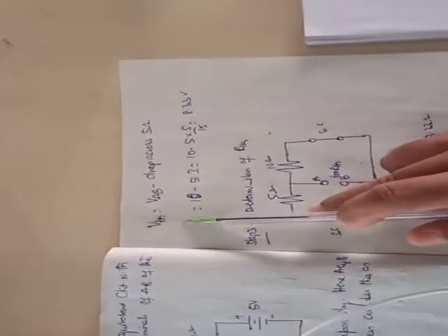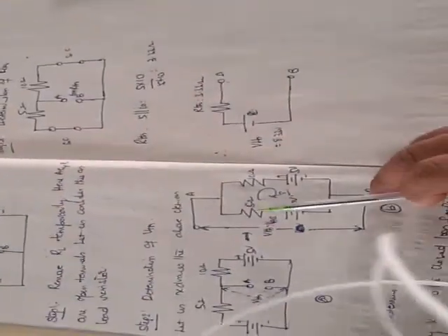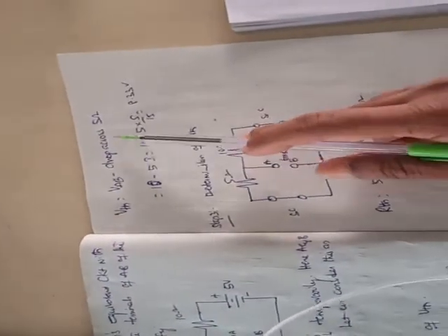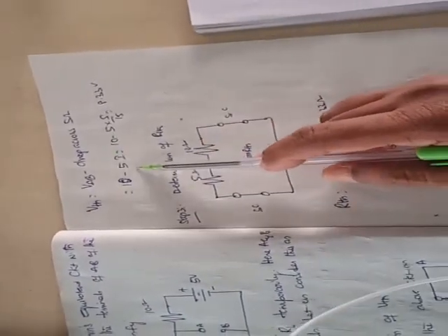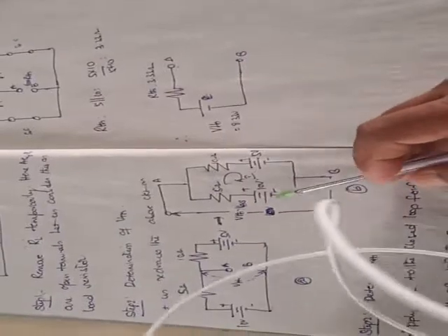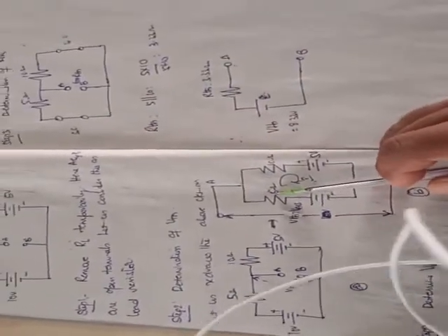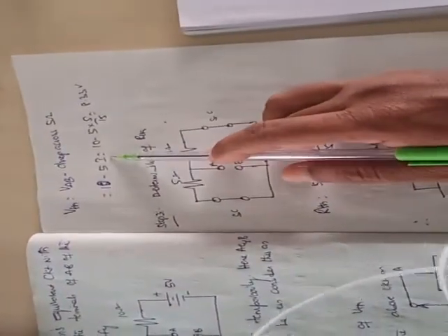That is, V Thevenin equals the voltage drop across the A and B terminals, that is 10 minus the drop across 5 ohms, that is minus 5 into I. 10 volts minus 5 into I.